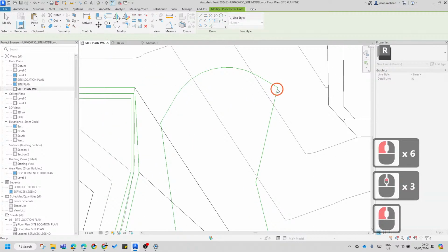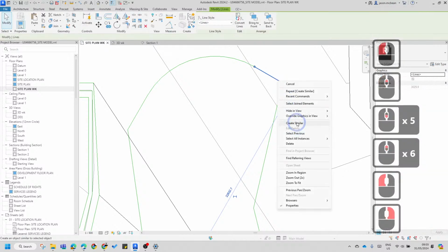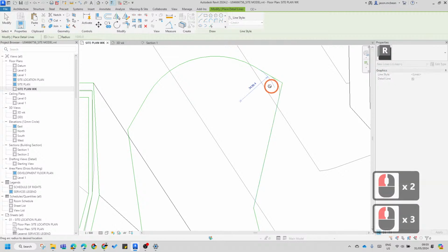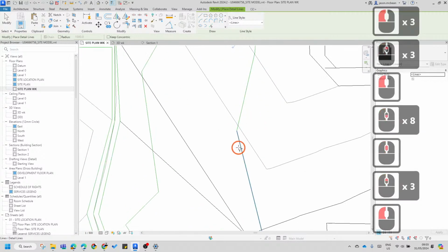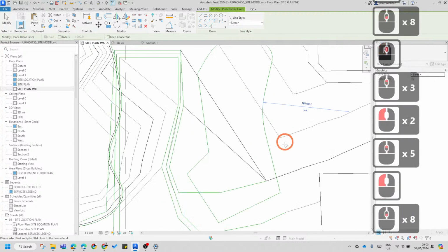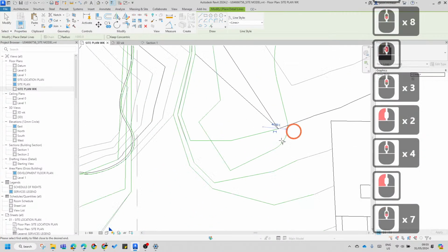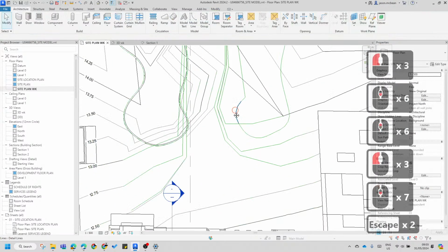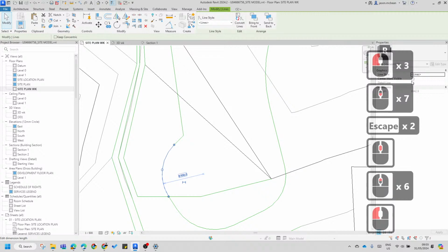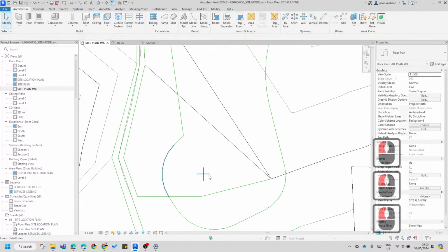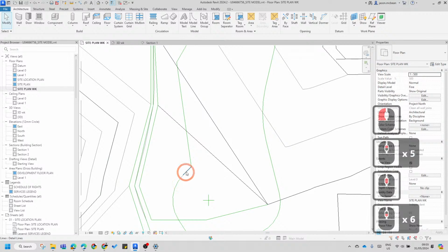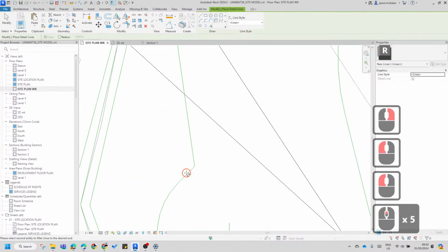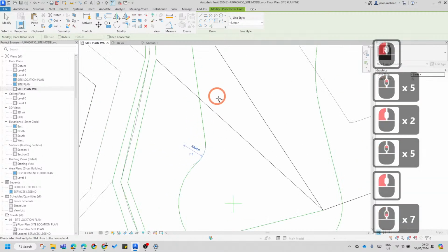Okay. And it'll limit you sometimes, I'll explain. So just create similar. So you get the line work more or less in the right place. And then I'll go and adjust the arcs a bit later. Just get the arcs in place. This way, mathematically, it gives you all the center points. Now, if you go and select this, you can switch on the center points. It switches on a mark for you, so you can use dimensions or grid to dimension this. Okay. Create similar. So sometimes you might have to, if you want to move elements around a bit.